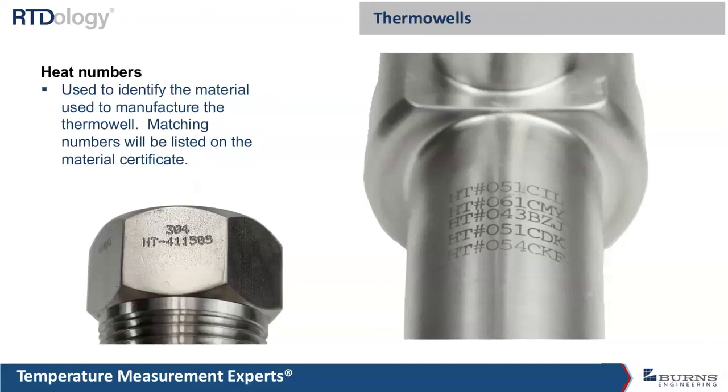Typically Thermowells will not have a serial number on them. This one over here, they stamped the material, 304 stainless, and then this heat number. And the heat numbers are going to be listed on the material certificate also, so you can match them up that way.